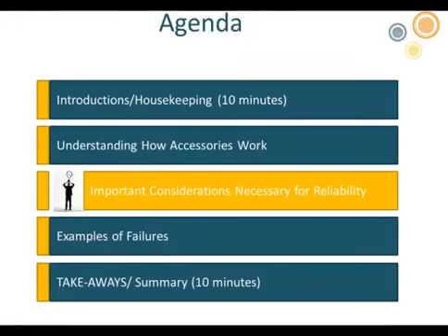So if you exceed the emergency operating temperature for an extended period of time, you're going to start degrading the material and cause it to degrade more quickly, and therefore not meet the expected life of the insulation or of the system. So excessive temperature typically always degrades polymeric materials more rapidly, and that's what reduces the life of the system. Okay, thanks.